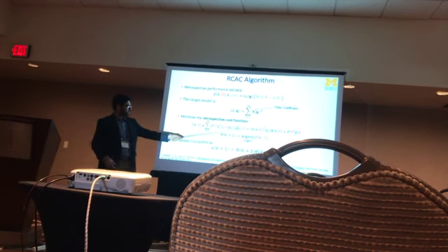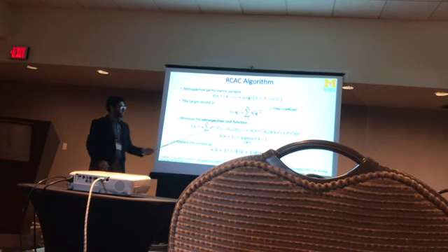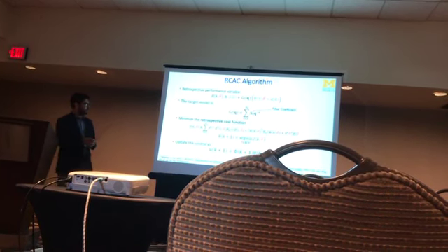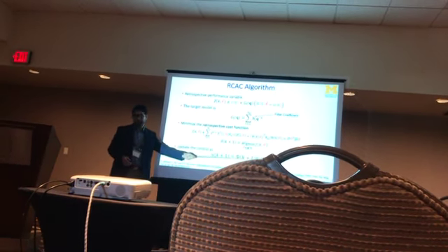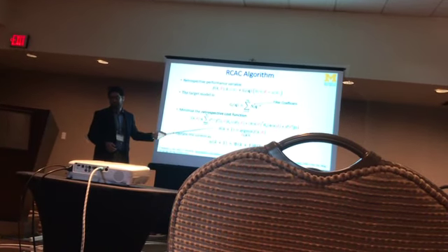And the minimizer of this cost function, which is shown in here, is what is used as the controller coefficient at the next step. So we set the control input at the next step as the data that we just had, and these optimized controller coefficients, which is the minimizer of this cost function.